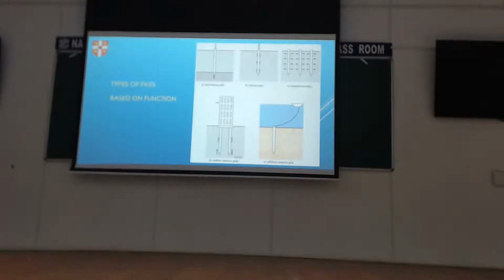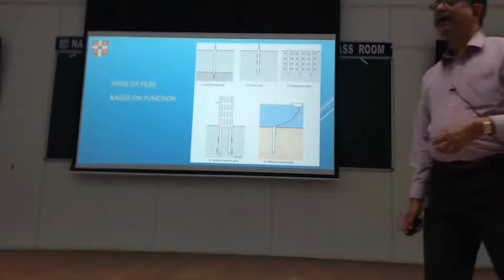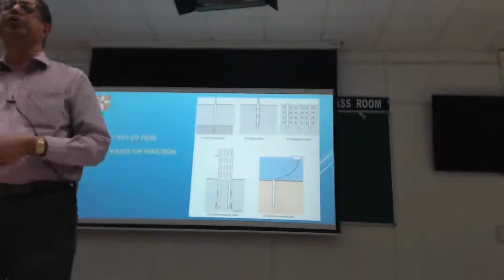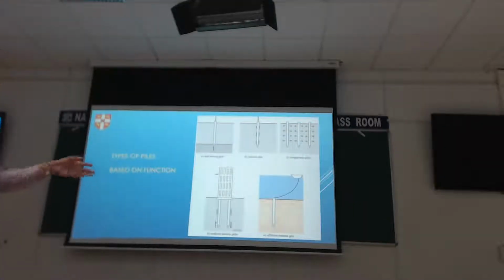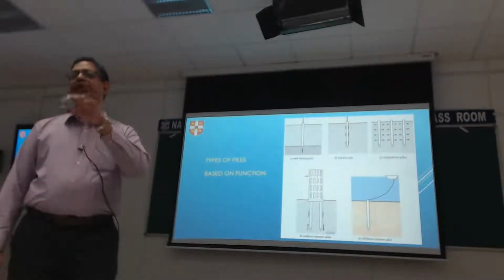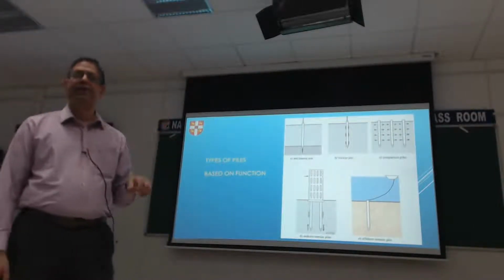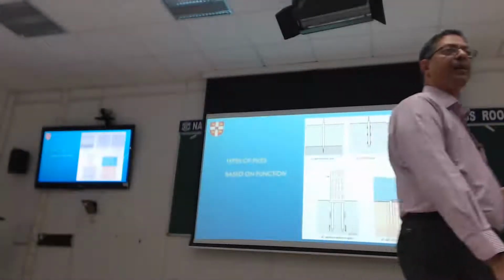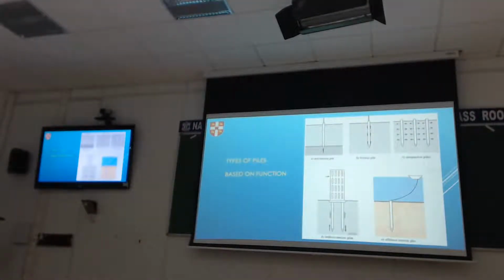You can have these onshore tension piles, and these are getting quite common these days, where you have to have the piles designed for taking both compression and tension. A typical example could be piles on either end of a raft, where rocking of the structure will induce axial tension in one of the piles in any half cycle. Under dynamic loads, this is quite possible.